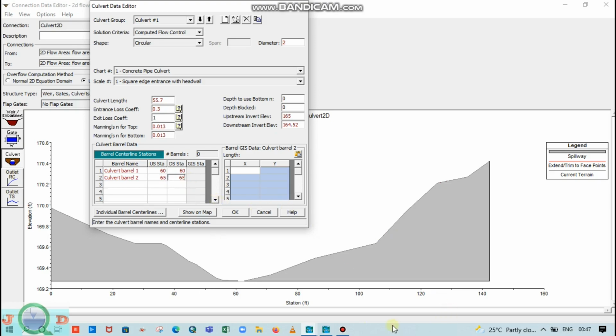This is a horizontal station. These are considered based on a horizontal station. So 60 feet is approximately where one culvert is coming, and this is the top surface of the deck portion of the weir or embankment, and below which the culvert is installed. We are installing the culverts.